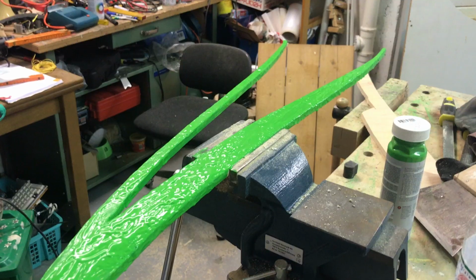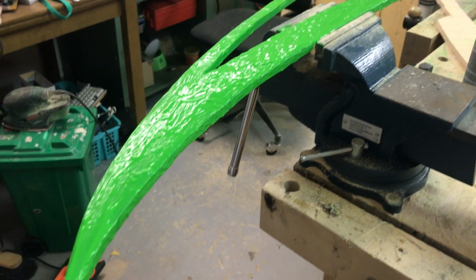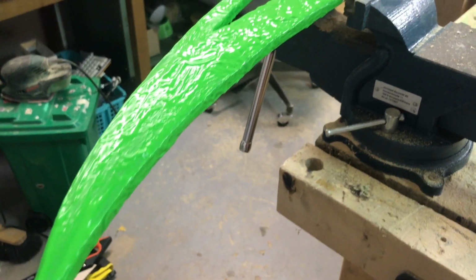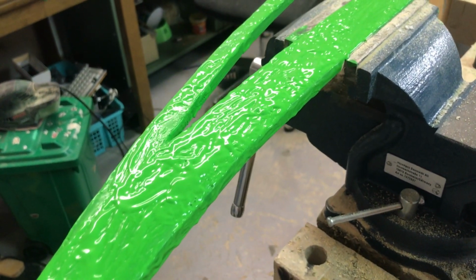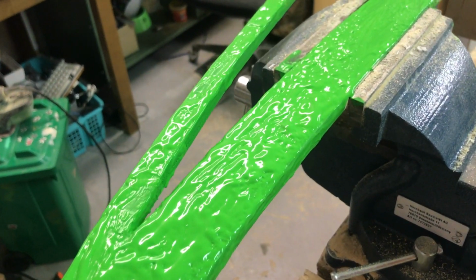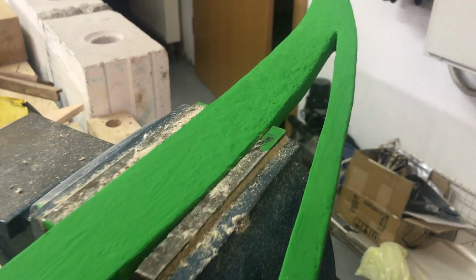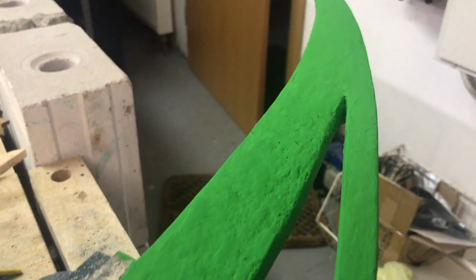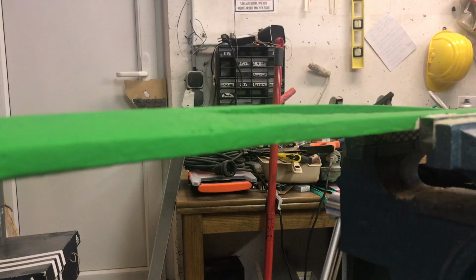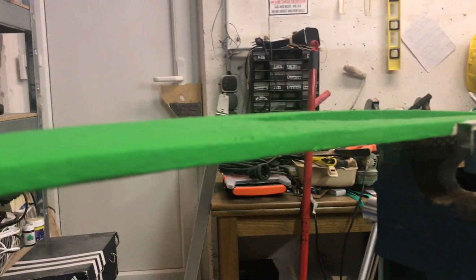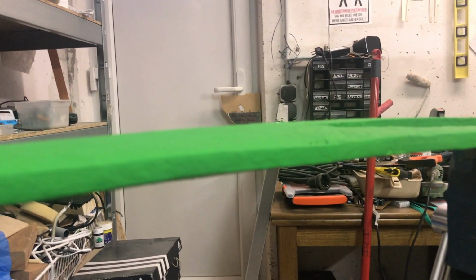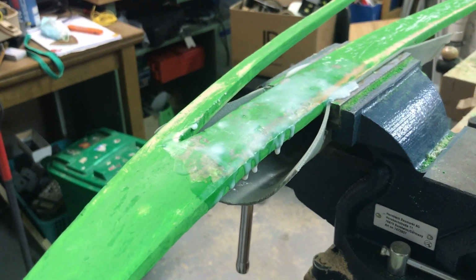You just paint the whole thing in multiple coatings, and by painting I mean really use lots of paint. Because in the end you want to have some substance that you can sand down so that you have a smooth surface. If after that process you're still left with some small gaps in the wood, just use an old candle and carefully drip the melted wax onto the surface.